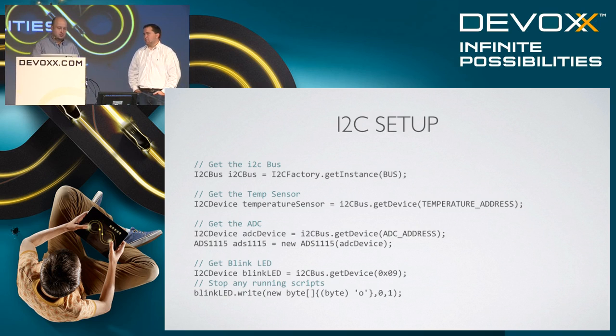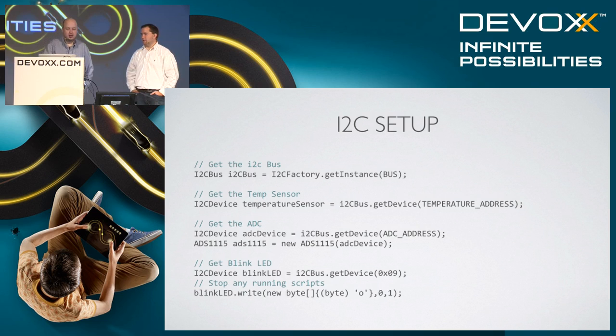So you just have these I2C devices, and they'll give you some data, and usually the data is in a very simple format. So the last guy is our I2C LED. There's a couple of different ways you can connect RGB LEDs up. You could use GPIO and do it that way. You can use an external pulse width modulation.